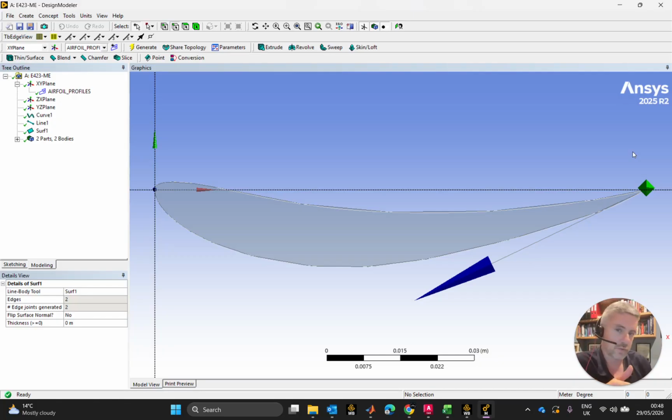or maybe direct it off somewhere, have a little bit more interaction with the end plates, or put strakes on in some case. But nevertheless, I want to leave a little bit of space for the conditioned air that's coming off of the airfoil to do its thing before hitting the wheel and the tire. So what I'm going to do is leave 6 inches, 150 mil, which would mean that this airfoil will be a maximum for me of 550.